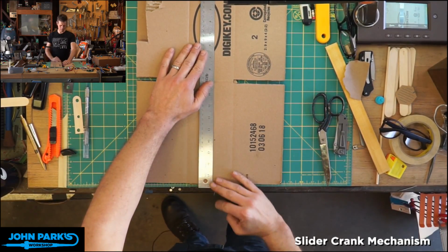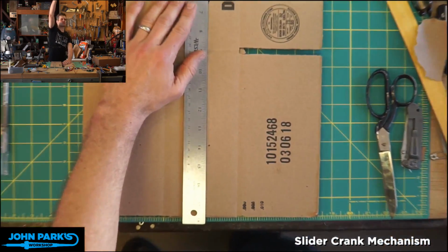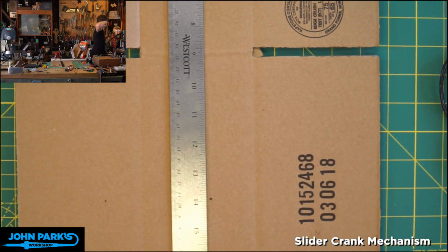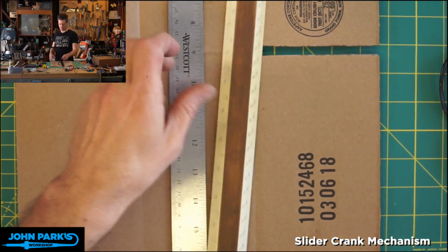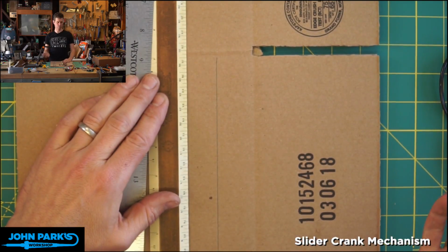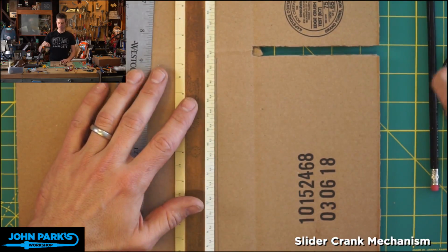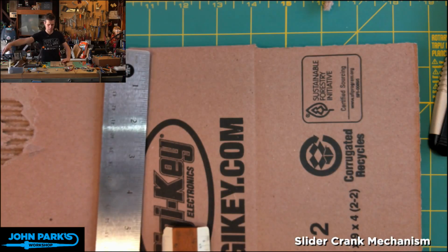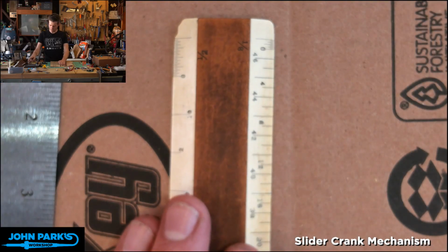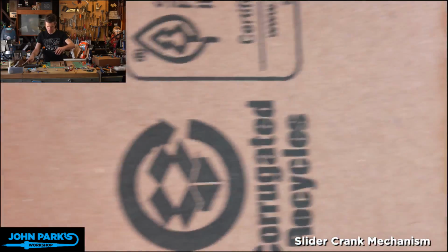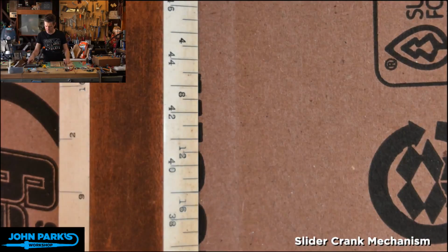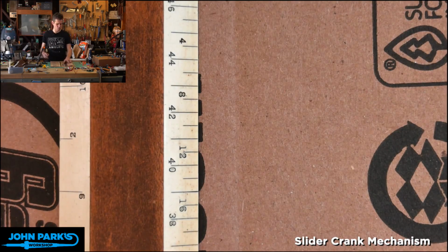And I recommend a metal ruler because if you use a plastic ruler, what tends to happen is you will slip. This is not for marking, this is for cutting. So any ruler or straight edge you want, you can go and mark up with a pencil to your heart's content. But what tends to happen with a plastic edge is that if you're using it to guide the blade, the guide likes to either cut into or ride up on top of that edge, which is actually dangerous.